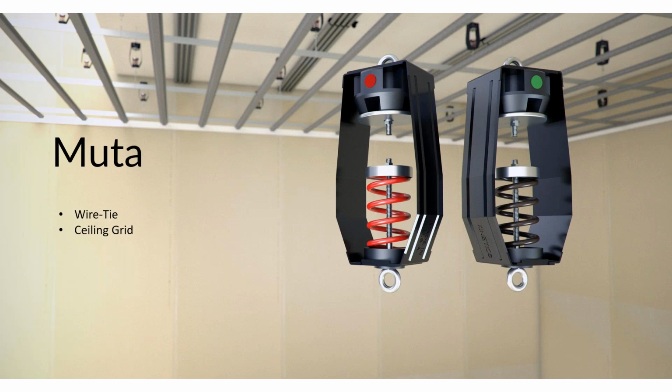What you have to watch out for is you don't want any hard attachments at the perimeter, and that's the first step of those systems. We can give you a detail with a resilient element in there, but you do have to watch that job site to make sure they've got it at the right place, because once they anchor that in, obviously it's not going to move.